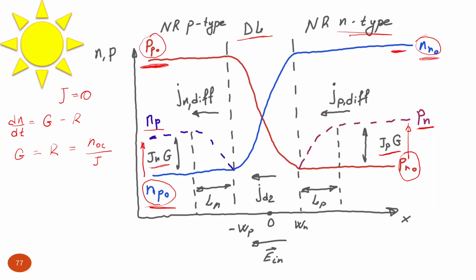Let's say this is for electrons, so we put tau n. So that's why the steady state concentration of photo-generated charge carriers under open circuit condition, n_OC, should be equal to tau n times G. So that's how we can determine the concentration of these minority charge carriers.